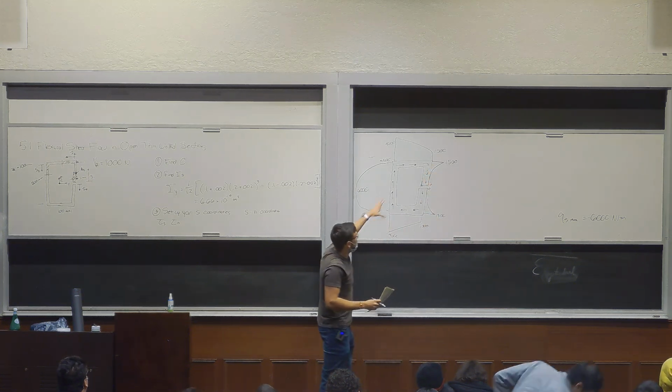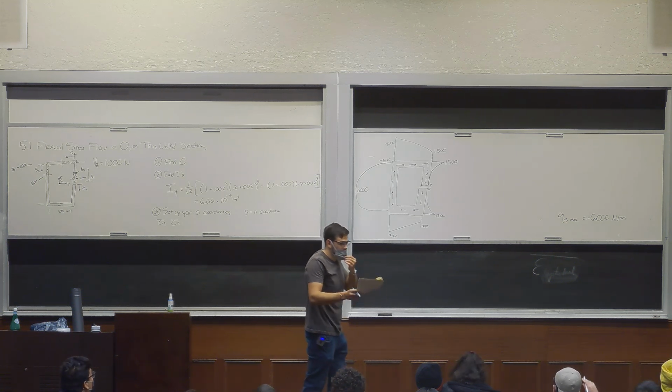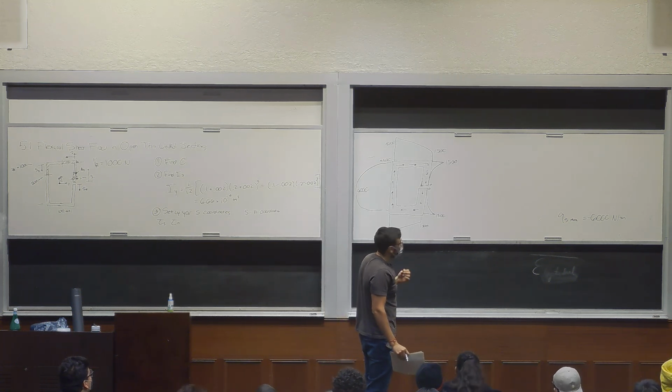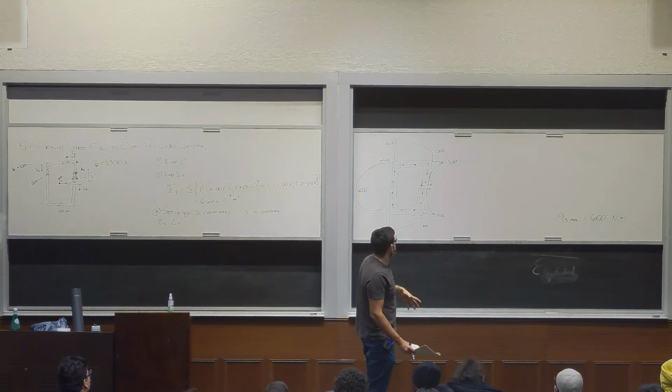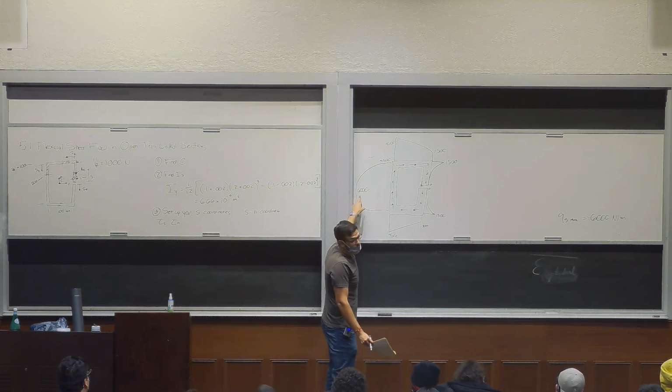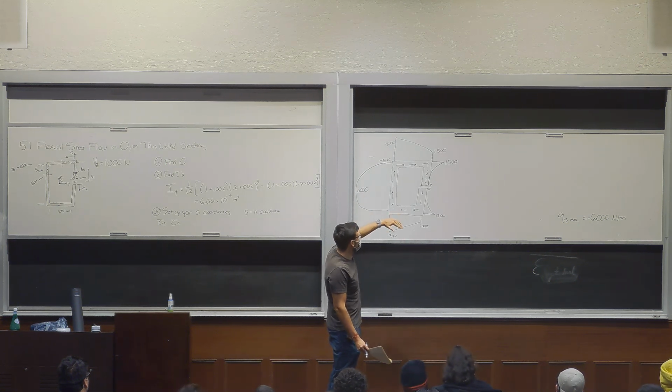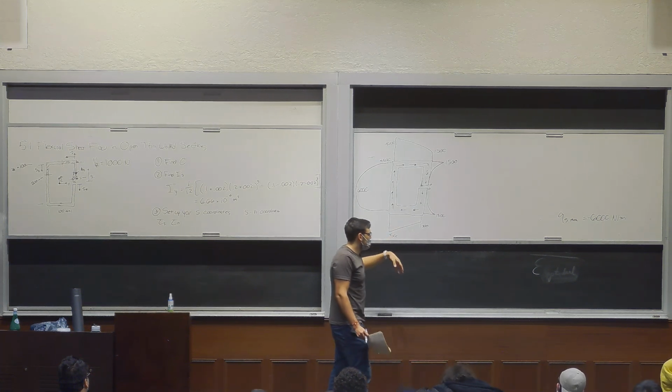Okay, so that'll be the direction. Of course, these arrows are not drawn to scale. Yeah, the numbers at the endpoints are important because those are typically the locations where it's maximum, right? For example, for this structure here, we would want to know that this is the maximum location of shear stress. Of course, you could have the distribution, but we want to know what the value is as well. The one thing is you don't have to draw the shape exactly parabolically or the slope. It doesn't matter. Just draw the general shape, whether it's linear or quadratic, and add the values.